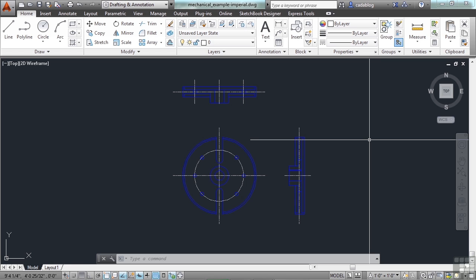It will only interpret the units when you go to print your drawing or when inserting other AutoCAD files or blocks. It will translate your drawing's units to fit the way you want it to look on paper. AutoCAD will take your line work and apply a scale factor when it prints. It will take the size of the paper you are printing on and scale your drawing objects accordingly.